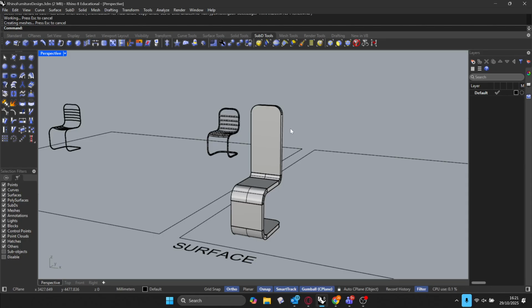So this is a really useful tip. In CGI, in architectural visualization, there are never, ever, ever sharp edges. We never have perfectly sharp edges. I want you to look at the desk in front of you. Okay? If we were modeling this desk, we would usually use a rectangle, but if you look at the desk in front of you, does it have a sharp edge? It doesn't have a really sharp edge. What would you say the radius is on this edge of this desk? So maybe 2, 3, 4 millimeters.